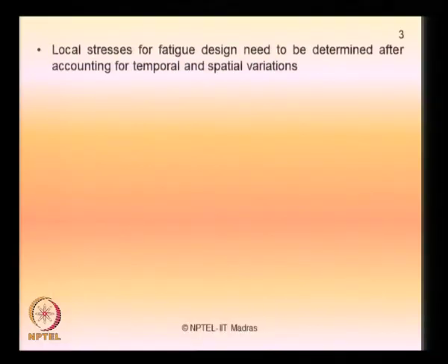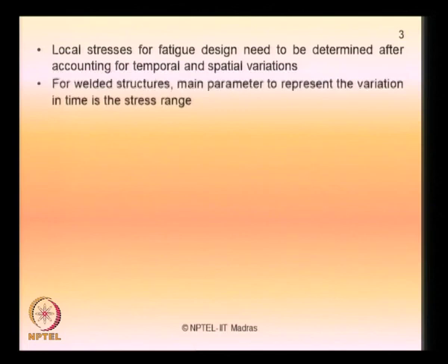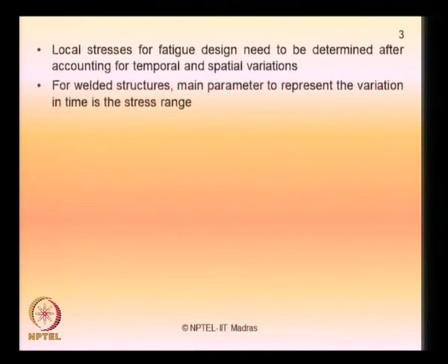The moment we talk about fatigue loading, local stresses for fatigue design need to be determined after accounting for temporal and spatial variations. It is very important that, depending upon the location where you are measuring these stresses, you need to account for that spatial variation. I will just show you a sketch where the hotspot stresses can vary for a welded structure.